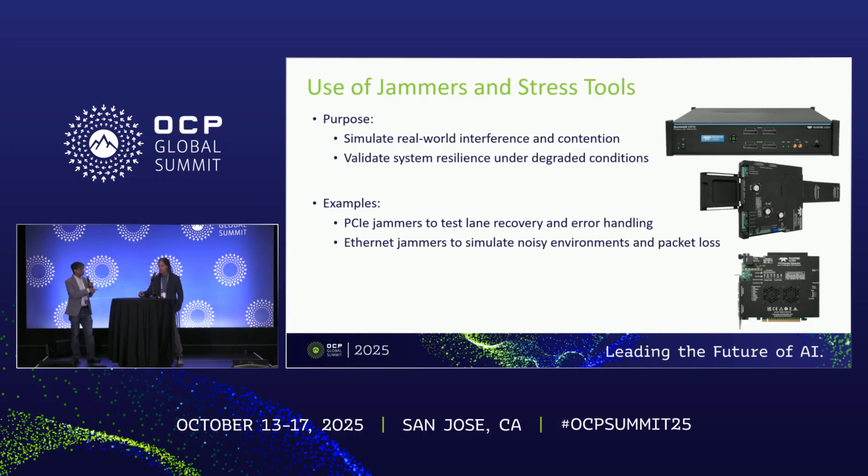So if I can interject just for a minute. In terms of the jammers, we did a lot of creative use of various jammers for error conditions. For example, with SCSI, we created a condition which would make the drive fail an IO command, but then we did a lot of manipulation of the sense data that is thrown back from the drive.